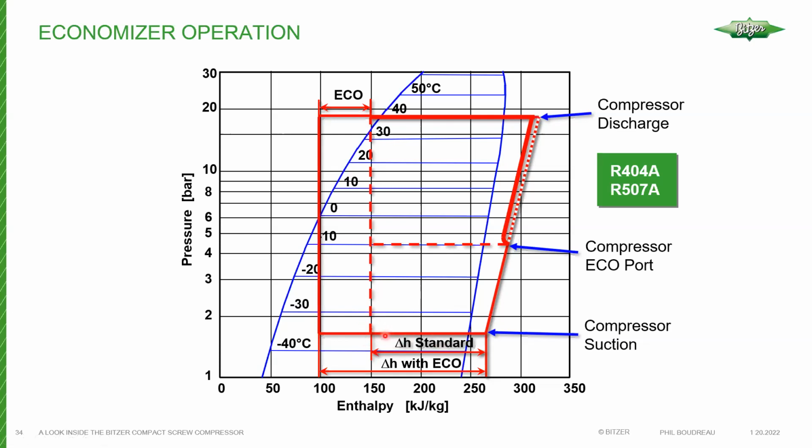But if we go back to the pressure enthalpy diagram here, we can see when we plot a cycle, it may look something like this. Doesn't matter what the values are. This is just to give you an example. So our actual net refrigeration effect that takes place in the evaporator is basically this much: the difference between maybe 260 kilojoules per kilogram, in this case it's metric, to 150. So that differential represents the net refrigeration effect. This, of course, represents your power input.